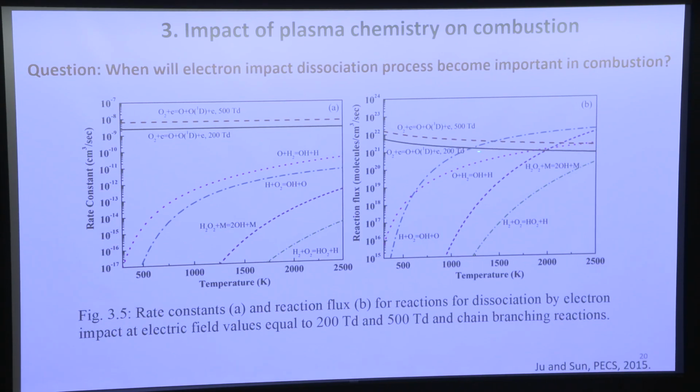Around a temperature of about 1100 Kelvin, when this reaction takes off, it produces radicals much faster than the strongest plasma we can do at 5,000 torr. That again comes back to my conclusion: if you have a very strong flame, plasma cannot compete with the H plus O2 reaction in combustion by itself.